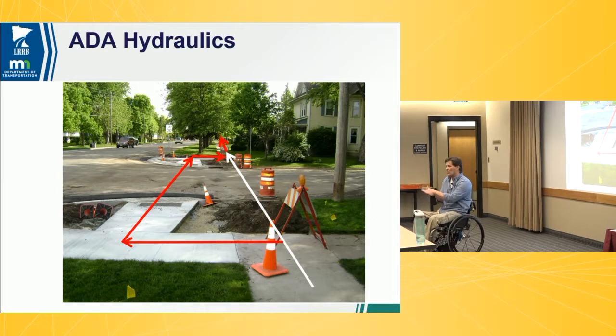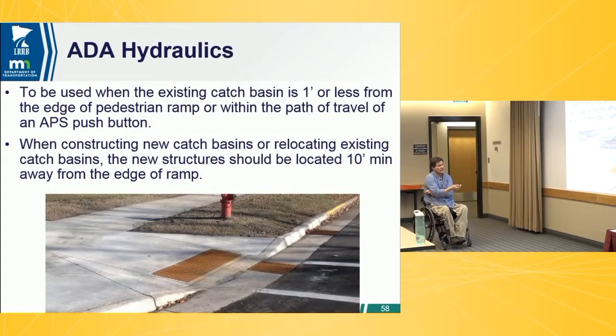And so you can wheel over that totally fine. And we're adding on a lead pipe 10, 15 feet away, shallow depth structure. So you can have that upstream hopefully and take the extra capacity, because that new grate reduces capacity about 50%. So when you add that helper structure, you've actually kept your sidewalk straight, but you actually have a 1.5% increase in hydraulic capacity. So again, here's a picture that shows that.